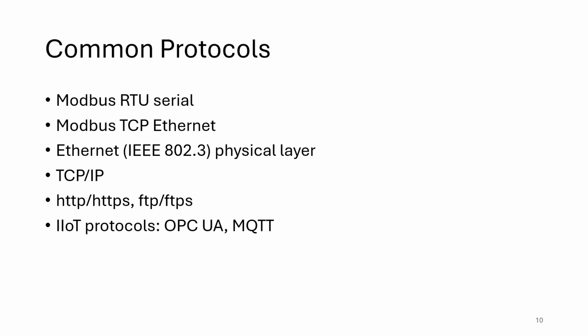Common protocols we come across: Modbus is one for industrial applications. Modbus RTU is a serial interface using the RS-232 or 422 or 485 physical layer, allowing one or up to a few devices to be connected over a simple local network.